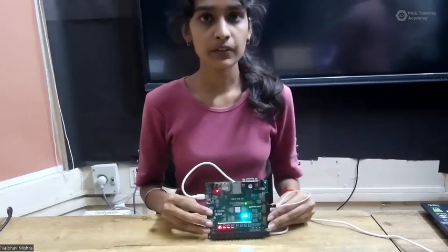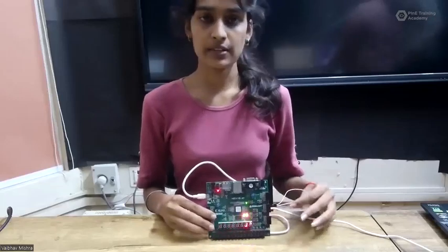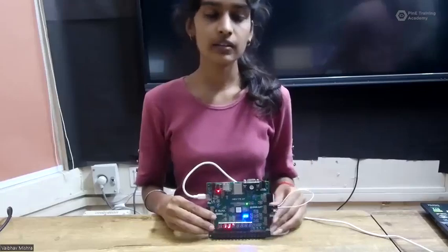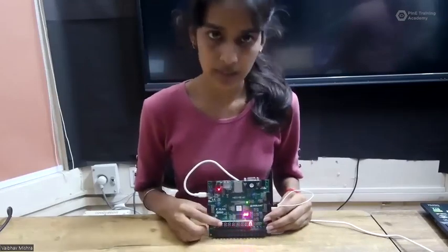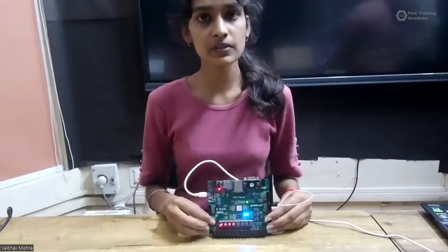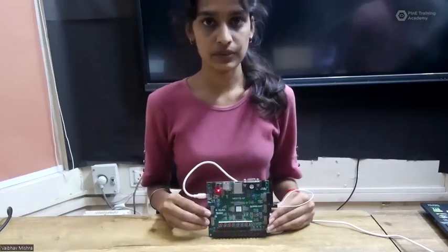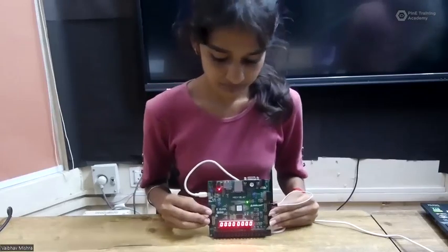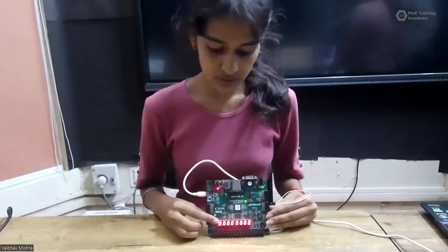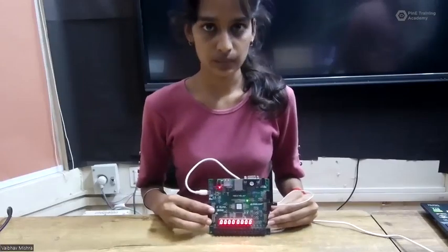Now, whenever we program our FPGA, first of all, we give input here. Then our data is transmitted serially. Then from the other end, we get our received data serially. And the received data is shown on the 7-segment display. We can also show the output on the LEDs, but for better visualization, we can see it on the SSD. Now it's time to program our FPGA. Here our FPGA is programmed, and at initialization, we got 0, 0, 0, 0, 0, 0, 0, 0 on the SSD because we have not given any input to it.